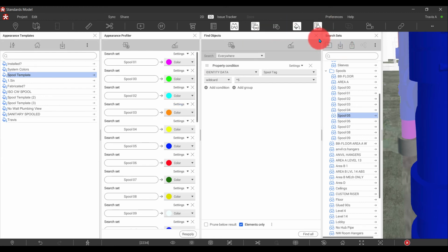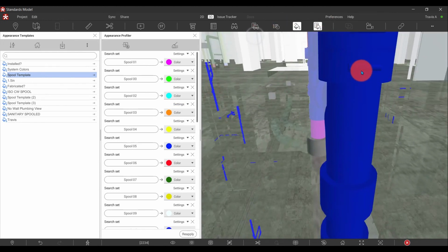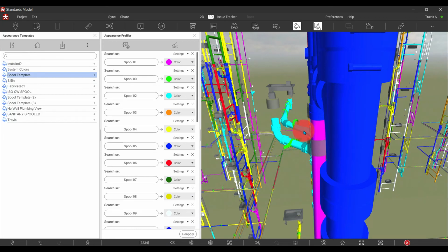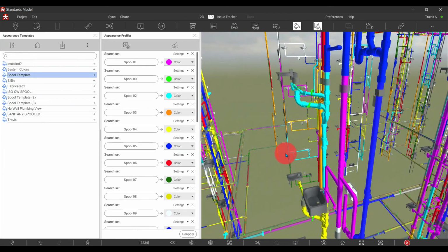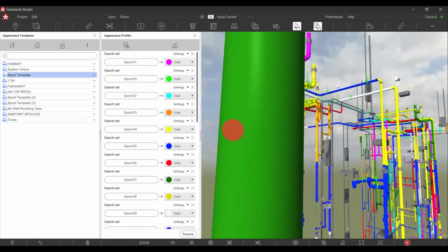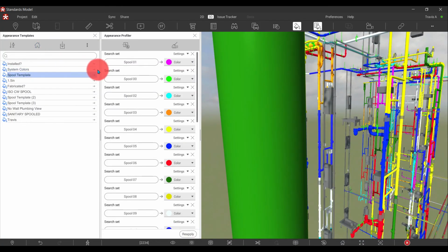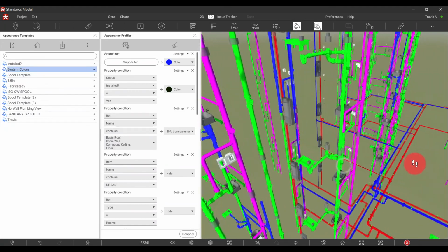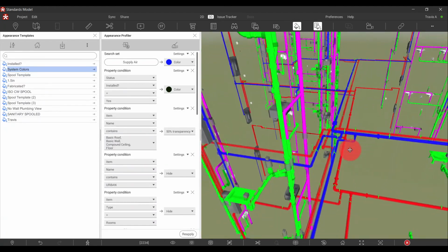And if the end user wants to see it a different way, you can right click in Revizto 5 and also unload everything but your model so we can have a nice clear isometric. But let's say they're looking at our piping isometric. This is all of our piping and plumbing in the job. And I'm going to come up here and run system colors instead. And here you can see, now I can see all my stuff in system color.